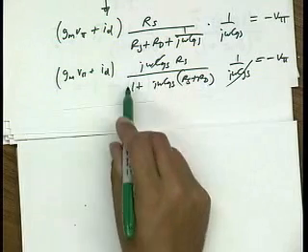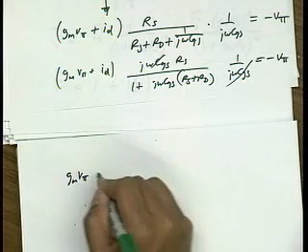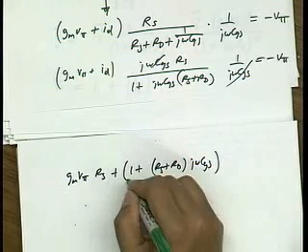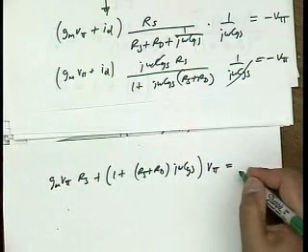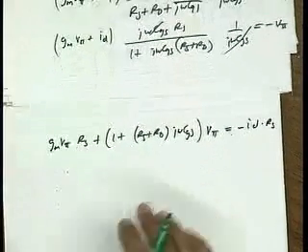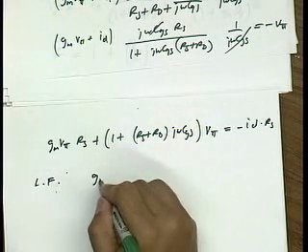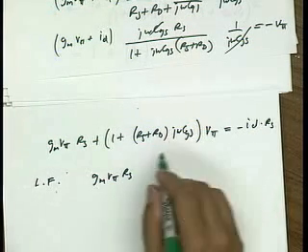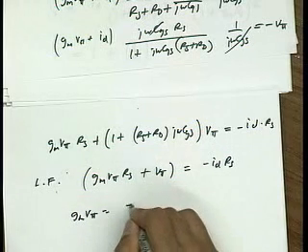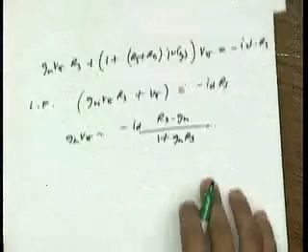So here, let me multiply this denominator on the right-hand side. So I have gm v pi RS plus 1 plus (RS plus Rd) j omega Cgs times v pi is equal to the right-hand side, which is just going to be minus Id times RS. And again, let's just keep the calculation simple. Let's go to low frequencies. So at low frequencies, I have gm v pi RS. This term is negligible, so I get plus v pi is equal to minus Id RS. And so gm v pi is minus Id RS times gm over 1 plus gm RS. Same exact expression that we got before,